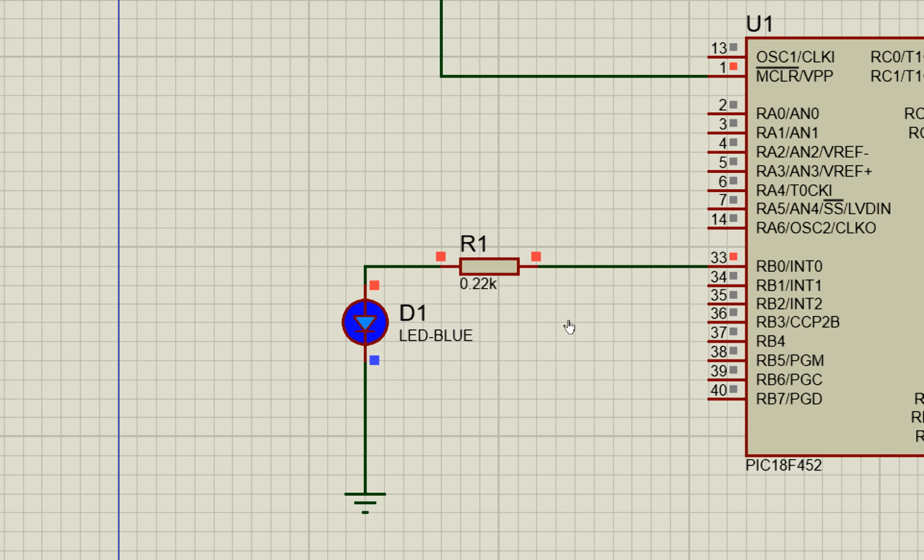You can see that in this way, guys, you can generate delays using a timer, and this is the most proper way of generating a delay, because in case of a delay command you are only using loop statements in the assembly, which is not a good thing. In case of long delays, and after a long period of time, if your microcontroller is installed in an industrial environment or somewhere, it will start to lose the timing control, because a loop is not a proper way of doing the job. So this is the proper way.